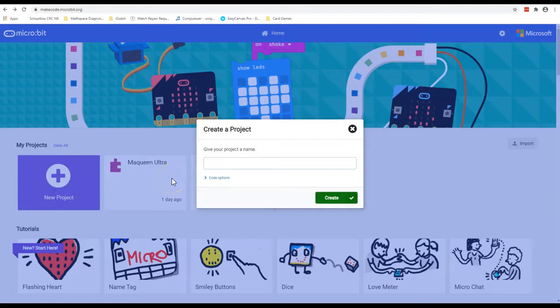The first thing you should always do is name your project, and you're asked to do that straight away. A good idea, as I usually say to my students, is to use your last name, then your first name, and then the name of whatever project you're doing. And this will just help to keep files separated, especially when you possibly hand them in to your teacher. So if I was doing this one, I would be doing Tomic, Nathan, and I'm going to be doing a counter here. So I'll put the last part of the name as the project I'm doing.